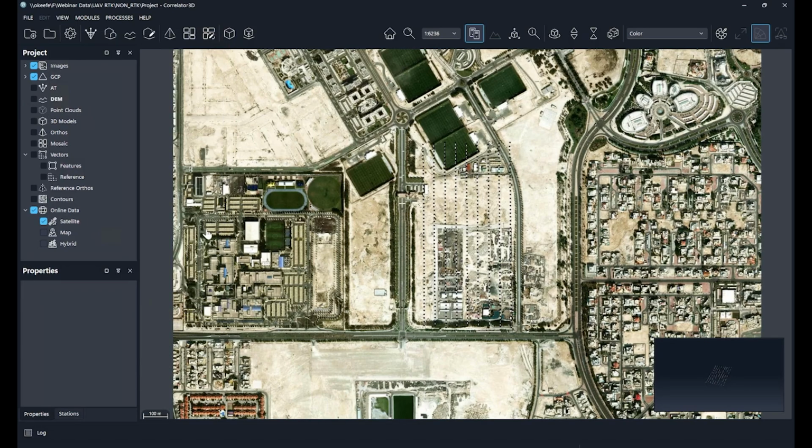We confirmed the projection, which was super easy. It was UTM, so nothing specific. So we had that part confirmed. No geoid applied, so they said, okay, just process the data, RTK, PPK, pretty simple.